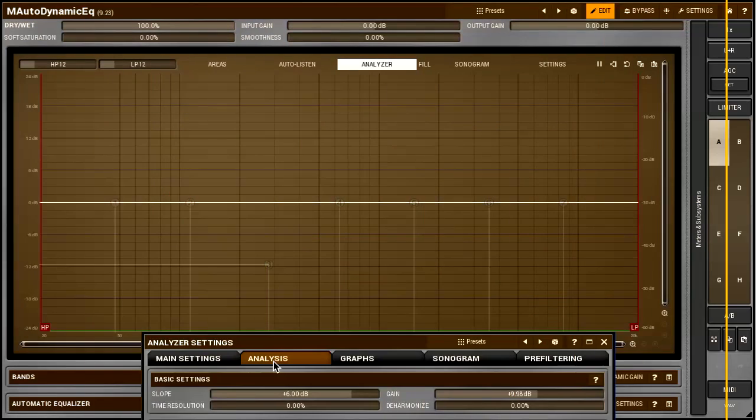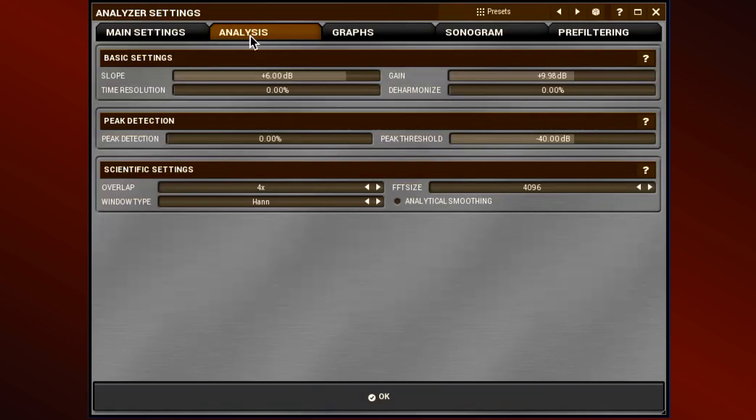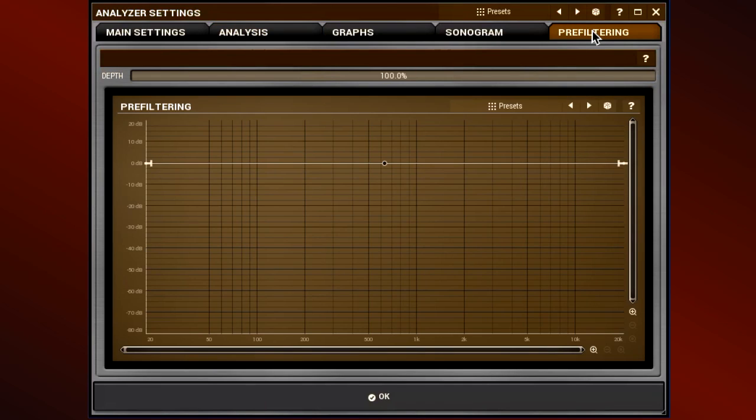As we're discussing the graph slope, I'd like to introduce you to a similar but much more powerful feature, pre-filtering, on the last tab. This is something no analog analyzer can touch. Here, we can literally draw a target spectrum shape by utilizing a powerful shape editor. And when the actual signal spectrum coincides with it, the analyzer will show a straight line. This is how it works.